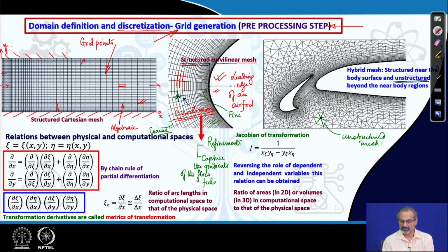You can very well understand that this kind of a mesh will be most well suited for a viscous flow calculation. So, a boundary layer will be formed on the surface, whether you are solving a problem like this on a flat plate or through a channel or over an airfoil, the boundary layer will be formed. So, the velocity variation will come up over here, and that too may be a very thin layer if it is a high Reynolds number flow. So, you need adequate grid resolution.